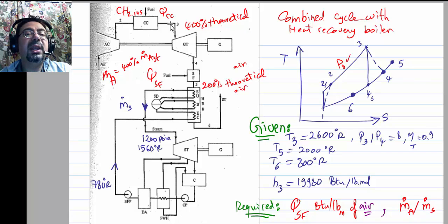When it's air with product, he can tell the right Cp for using this. Okay, so that's just more accuracy. And so the air here is 400% of what's required, meaning that this is Cp air, but over here that is air with product. And how much product? 400% air ratio. That tells him how to use the table with the right amount of product in the exhaust.